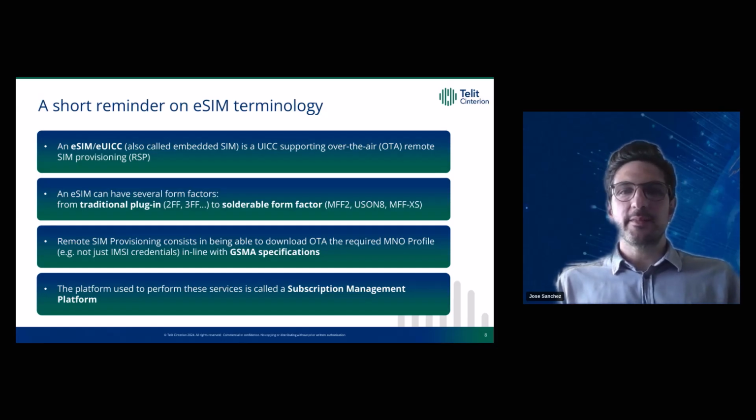And an eSIM can have several form factors. So an eSIM is not only a solderable SIM. It can be also a plastic SIM in the context of any kind of application. You have eSIMs today as plastic SIMs or pluggable SIMs, or as solderable SIMs, and available in multiple form factors.